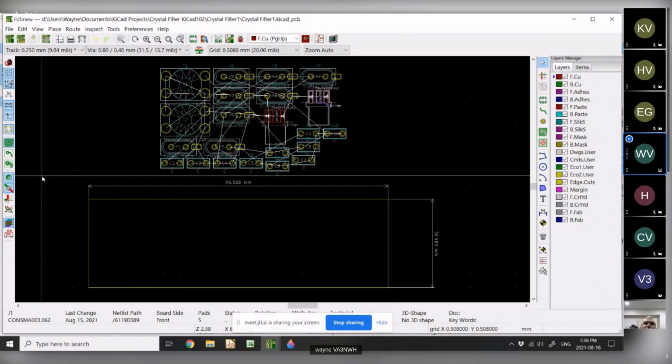And to describe what I'm going to do is I'm going to make this for manufacture, and I'm going to demonstrate the steps that you go through to set it up, to set it off to a manufacturer. And as such, the one thing you probably need to know is something about what the manufacturer says it can do. I'll explain it this way. There are some features of KiCad that allow you to set the smallest line width, or the closest distance between pieces and stuff of that nature.